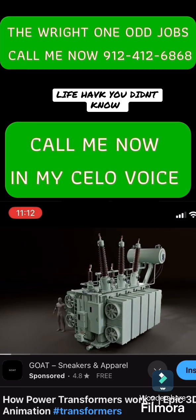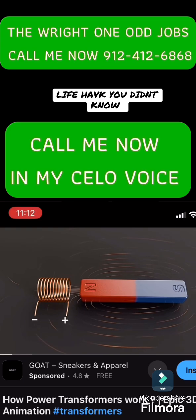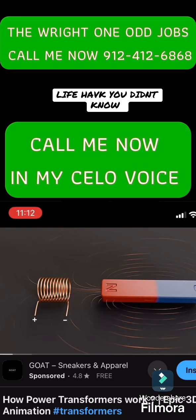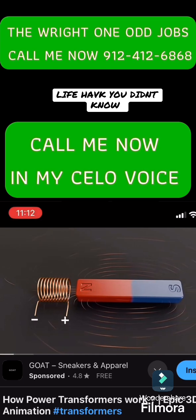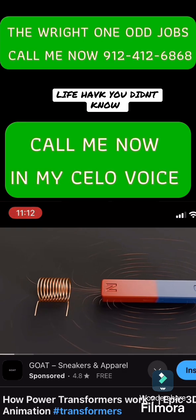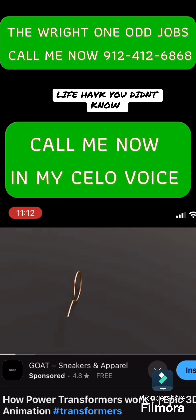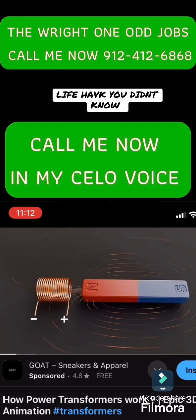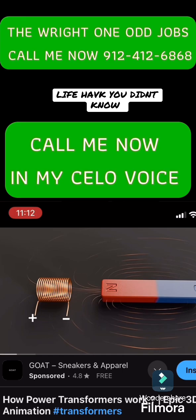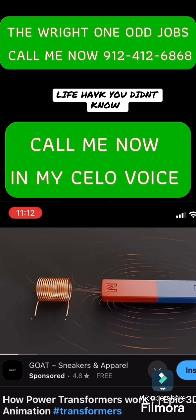Before diving into the working of a power transformer, let's first take a look at the fundamentals of a transformer. When we move a magnet near a coil, a voltage is induced in the coil. This occurs due to a change in the number of magnetic field lines passing through the coil, or alternatively, we can say there is a change in magnetic flux linking with the coil. This phenomenon is known as electromagnetic induction. The strength of induced voltage depends upon the number of turns in the coil, the strength of the magnetic field, and how fast we are moving the magnet, or we can say, the rate of change of flux linking with the coil.